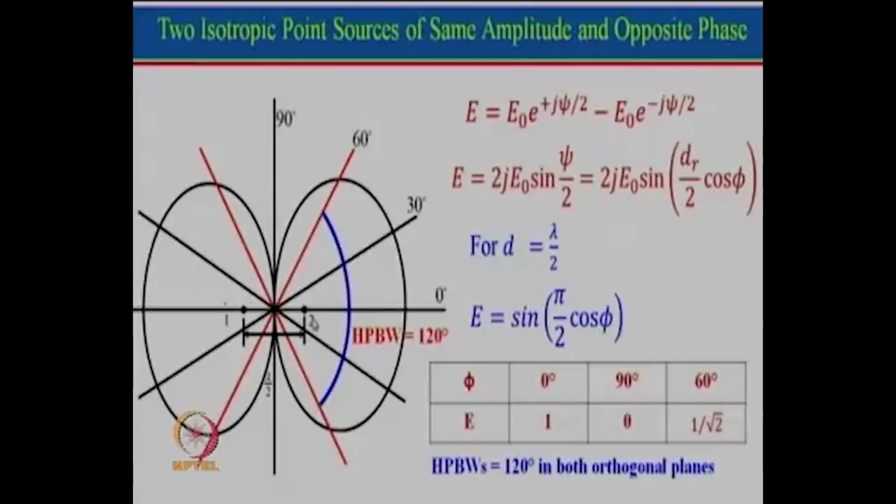So basically what happens, if you excite one antenna, some field will be induced on the second antenna, and if the second antenna is excited, some field will get induced on the first antenna. So if we take a distance as lambda by 2, the impedance effect is almost negligible. That is why we take lambda by 2. But later on we will see what happens if you change the spacing, what is the effect on the gain, radiation pattern, and so on.